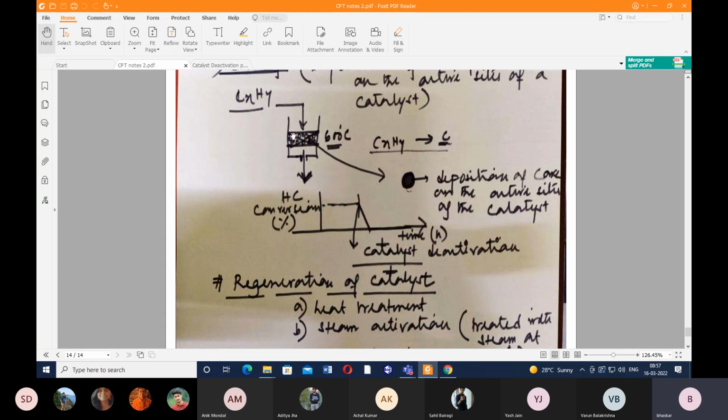After regeneration, again we will feed these catalyst pellets inside this bed, and we'll further carry out the reaction. These reactions are continued in a continuous manner. These are not batch processes, right? So continuously we want to feed the reactant for 1 or 2 years without any delay, without any problems or troubles. But when we're handling the hydrocarbon feedstock, we always encounter this coking problem.